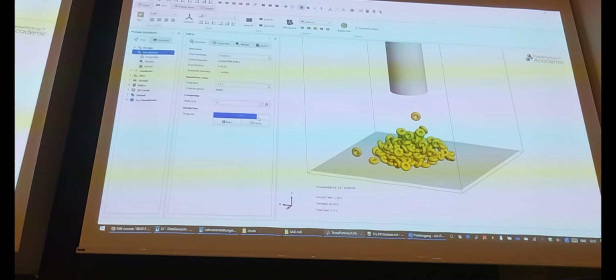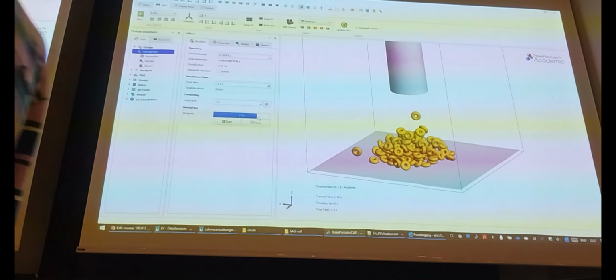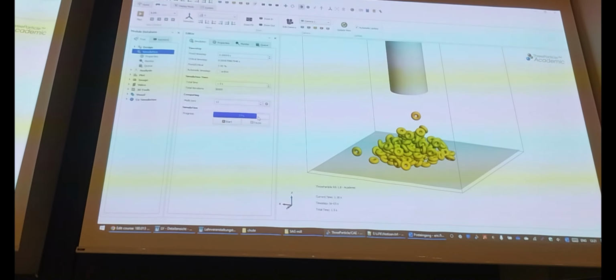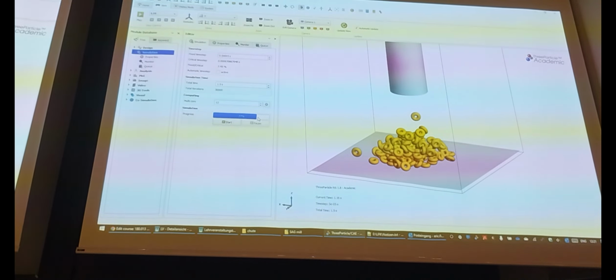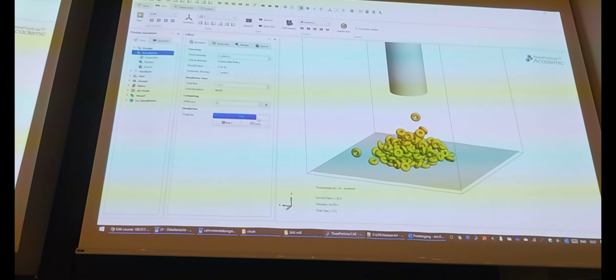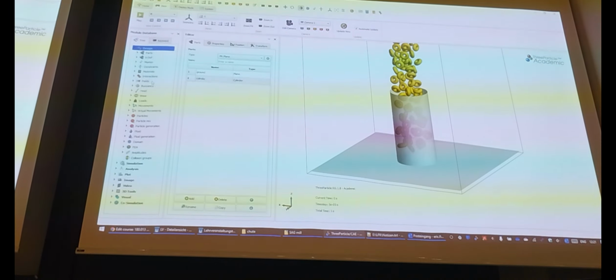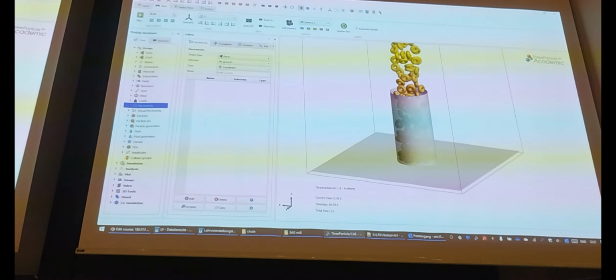So, the question was, if I change something at 0.5 seconds, for example, lifting of the cylinder, and I go back to second 0, the lifting is not there, right? Yes, and that's the case. So I typically, when I know I want to lift the cylinder later on, I define from the beginning the movement. And if you can see here, no movement there, right? Because it's not defined yet. And if I proceed on, at 0.5 exactly, there is the cylinder lifting suddenly appearing. You can see that? So it's not there yet.